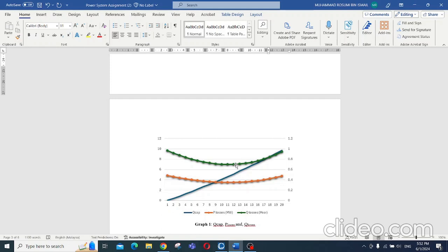For Q cap values from 3.6 to 5.7, P losses decrease from 0.701 to 0.360, and the Q losses decrease from 0.710 to 0.721. In practical terms, Q cap values between 3.6 and 5.6 could lead to minimized power losses and higher overall power system efficiency, as indicated by the evaluated power factor.